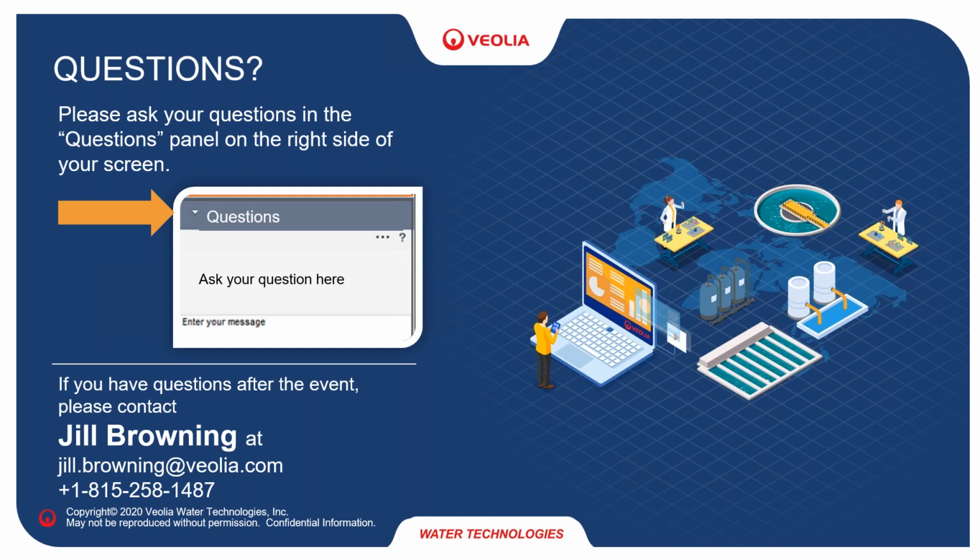And now what's the limitation, the lowest temperature? We tested as low as 3 degrees Celsius in that case study, and we were limited to make sure there's no freezing. In some municipal applications, they go lower than 1 degree Celsius. Well, the limitation is you don't want MBBR to freeze. You don't want the water to freeze. But is there a limitation? We haven't found one yet. This is the real answer. We have not found any limitation yet.